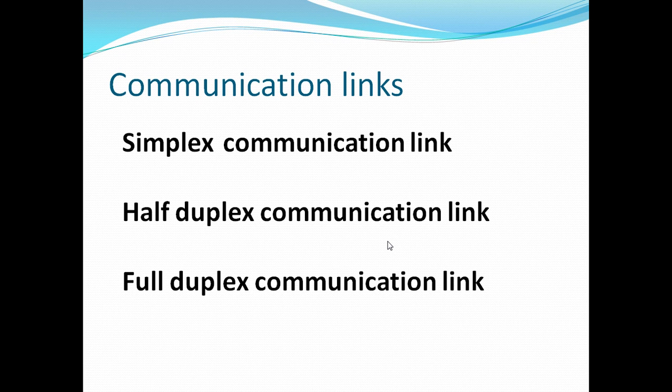And the third and last one is full duplex communication, in which we can do data transfer operation from transmitter to receiver and receiver to transmitter at a time, a single bit in each direction. So here two wires will be used for serial communication. One will transmit and the second will receive. So two pins are required to have data transfer between electronic devices.